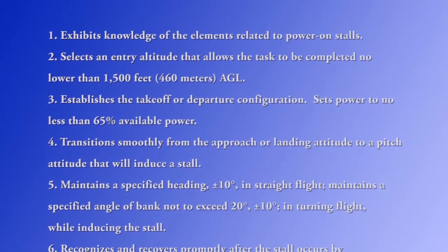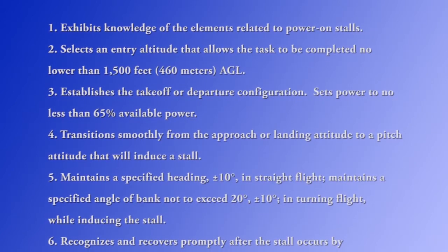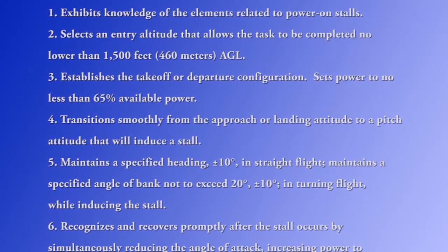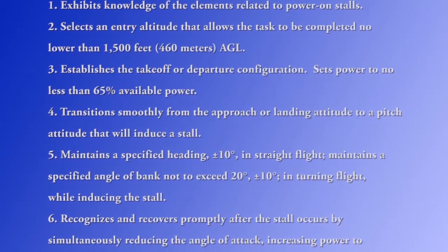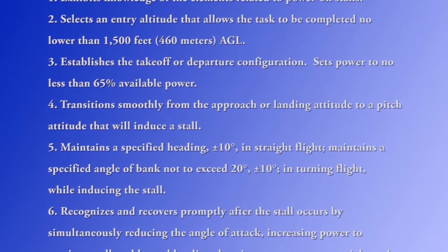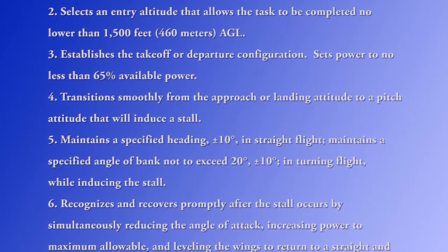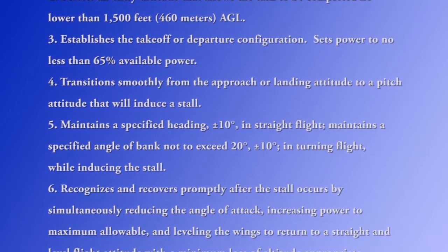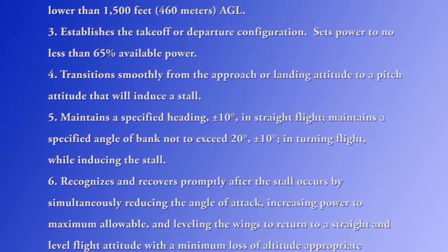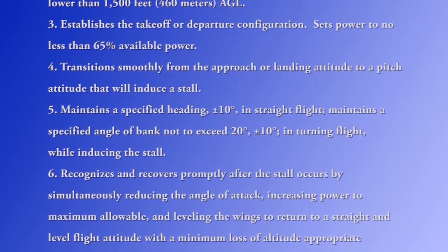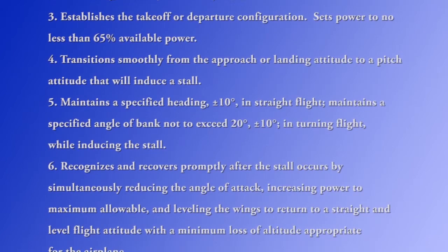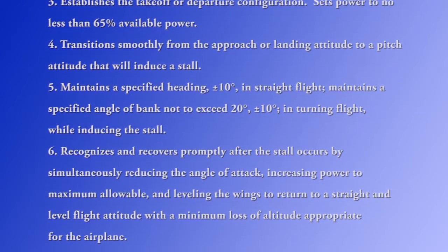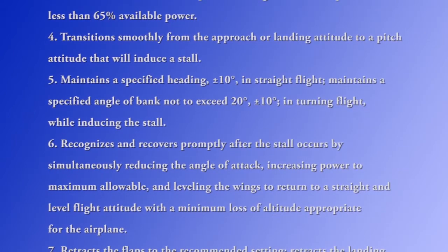Transitions smoothly from the approach or landing attitude to a pitch attitude that will induce a stall. Maintains a specified heading plus or minus 10 degrees in straight flight. Maintains a specified angle of bank not to exceed 20 degrees plus or minus 10 degrees in turning flight while inducing the stall. Recognizes and recovers promptly after the stall occurs by simultaneously reducing the angle of attack, increasing power